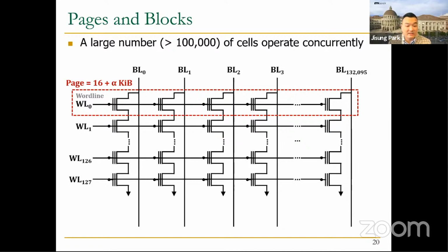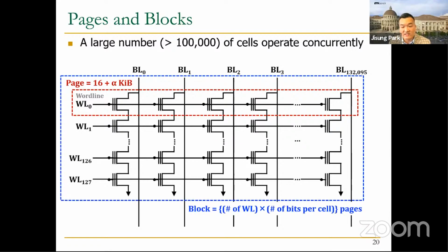And cells in the NAND string that are connected to the same word lines comprise a block, the unit of erase operations. So the block size should be the same as the multiple of the number of word lines and the number of bits stored in a single cell.